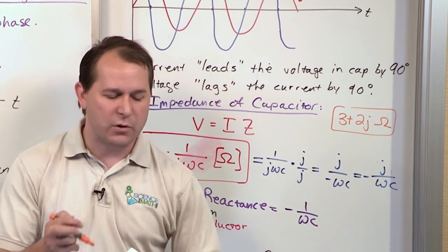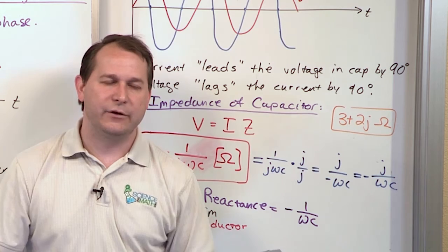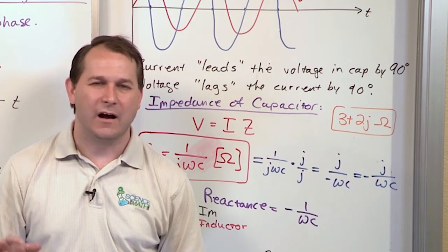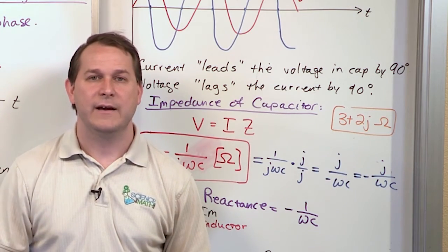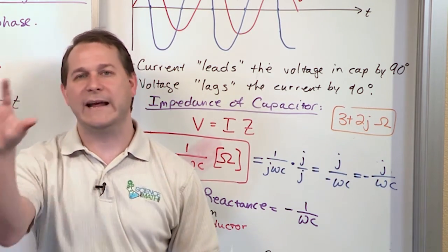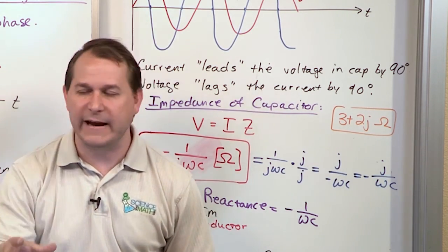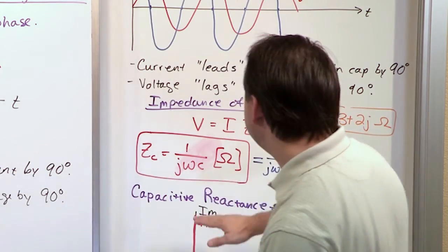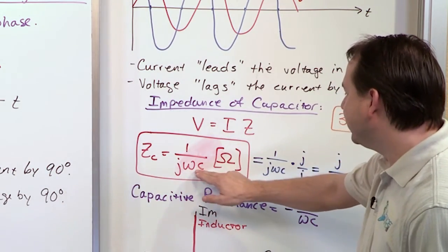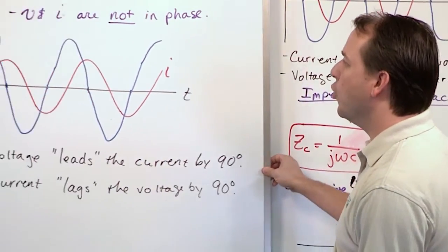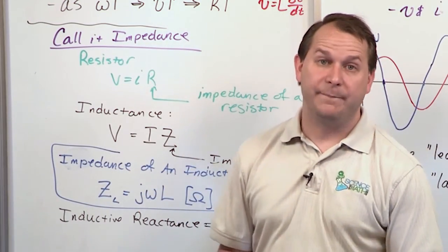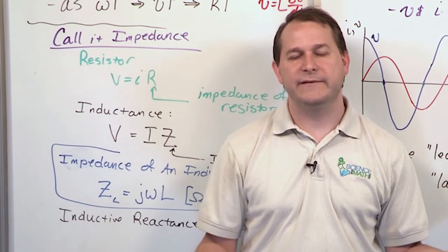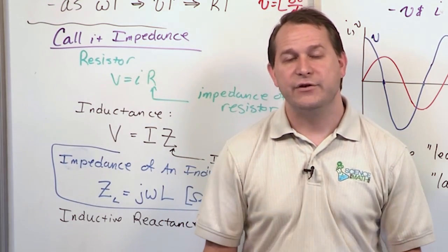But even though I'm giving you all of these details, and even though I think they're cool and important, honestly the only thing you really need to know out of this section and the last section is that in a few sections, we're going to start analyzing circuits. The resistors stay the same. For the capacitors, you use an impedance of 1 over j omega C, in ohms. And for the inductors, you use j omega times L. We replace all the components with our impedances, we do our analysis, and we're done. And you'll see that it's pretty easy.